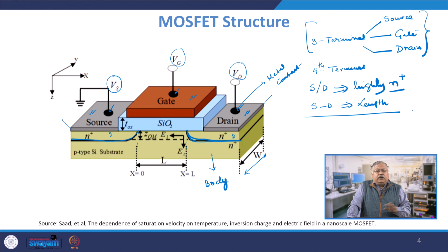Ideally, if I do not do anything else and everything else is common, then the gate length and the channel length capital L match with each other, and these are known as self aligned structures in a sense.